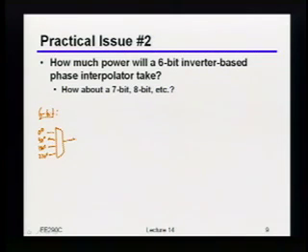So now if I just want another 4 bits of resolution, how many legs do I have in that variable width inverter that I'm drawing up here? I'm just not going to draw them all, but how many legs do you have in that upper thing right there? 16. Yeah, you have 16, because I already knocked off 2 bits of resolution.